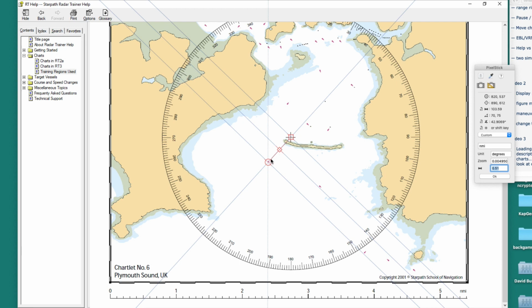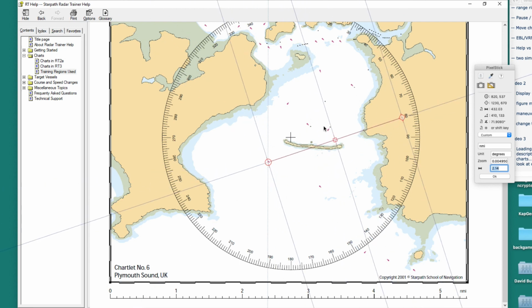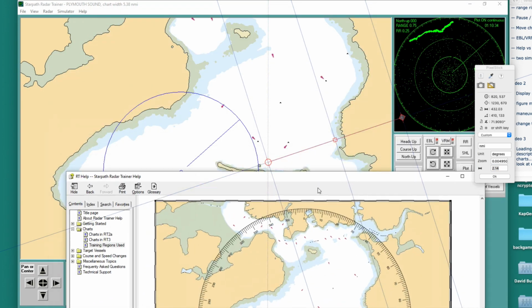You see here, this distance from here to here, you would put your dividers on here and measure. You're going to get fixes out here, radar fixes. And once you get a radar fix with an intersection of either bearing and range or 2 range rings or something, you're going to get a fix. And then once you have that fix, you want to tell your answer as the range and bearing from this center point. And in this case, the answer would be 0.51 miles in direction of 223, and so forth. So that's how you would use this chart, just like a regular chart, using parallel rulers and dividers, like that.